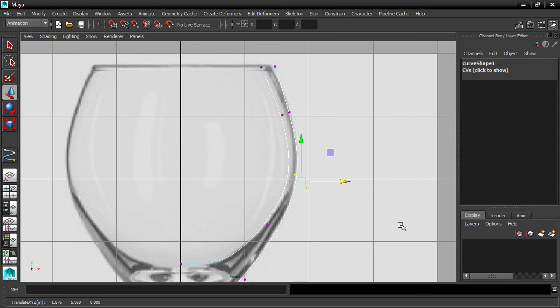If you want to add or remove points on a NURBS curve, there's a process for that. If you want to remove points, it's really easy. You just select a point and press delete on the keyboard, and it gets erased. Notice that it will change the shape of the curve. If I want to undo that, I can just press Z on the keyboard, and that is undo. To insert points is a more involved process.